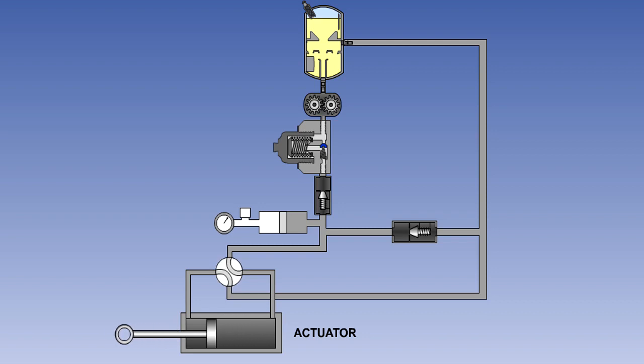And as we shall see later, some types of hydraulic actuator need more fluid when they are extended than when contracted. The extra fluid is stored in the reservoir when not required. Most hydraulic systems also have accumulators fitted, and these will contain variable amounts of fluid depending on the system configuration. Again, we will discuss these in greater detail shortly.